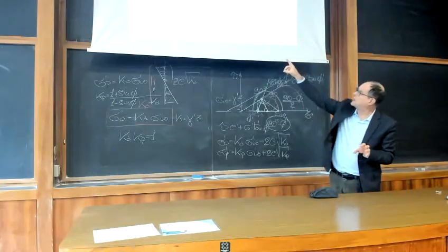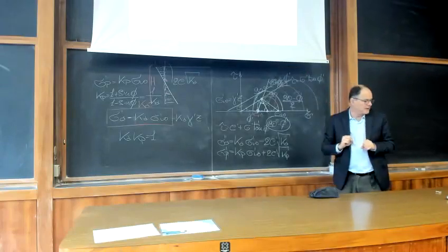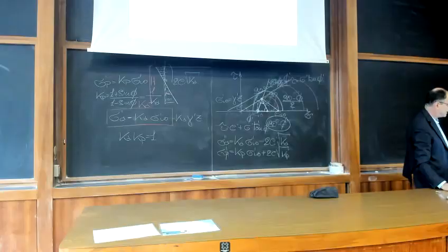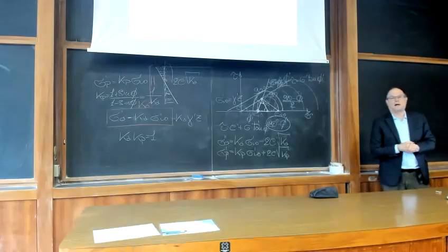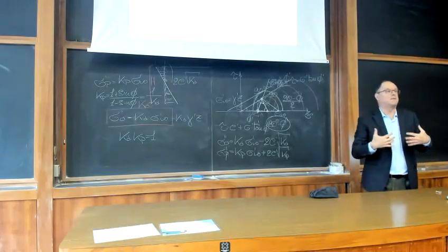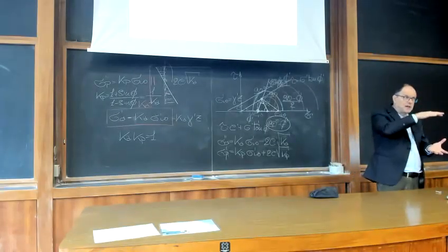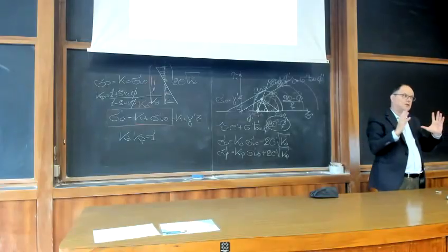And if you look at the left-hand side figure, you can see that if this is a foundation loading, this is typically what we expect and what we have described last week as a foundation loading. So you typically increase the vertical stress and you do not increase the horizontal stress.